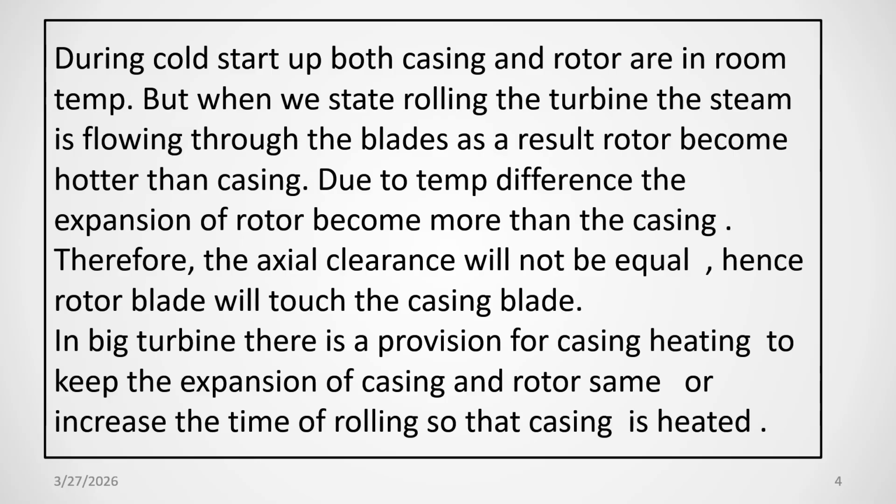While the casing is standing still, there is a guide blade carrier, then the casing. So the casing will take some time to reach the same temperature. So there will be a temperature difference between the turbine rotor and the casing. Due to the temperature difference, the turbine rotor will expand more, and the casing will not expand as much. So whatever axial gap we maintained while assembling the turbine with the casing may get disturbed, and the turbine rotor may touch the turbine casing. So there will be rubbing marks and high vibration.